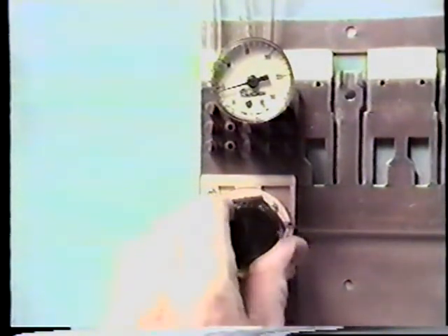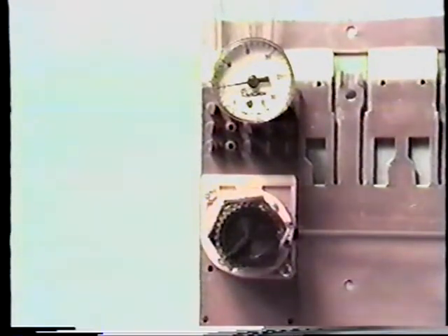Now we can set the minimum position switch to maintain a 5-pound minimum signal on the dampers, which will provide the minimum amount of outside air for ventilation purposes. Anytime the signal at S1 port is greater than 5 pounds, it is transmitted to the actuators to cycle them between the minimum and the full open position.